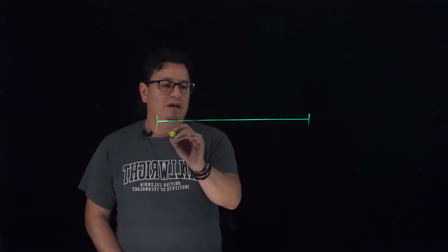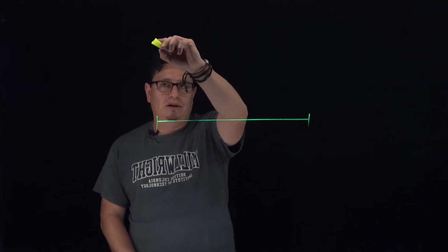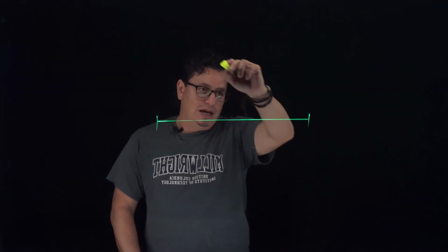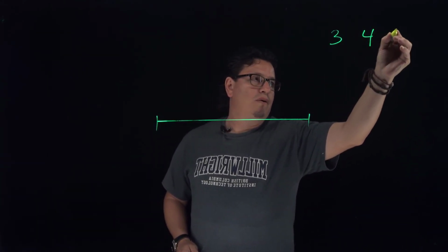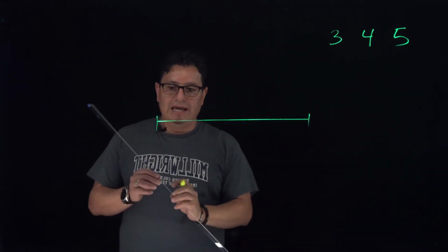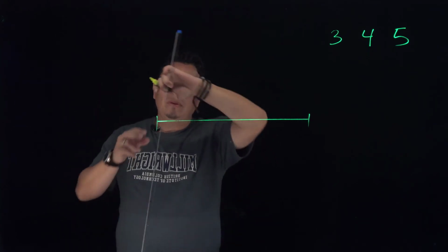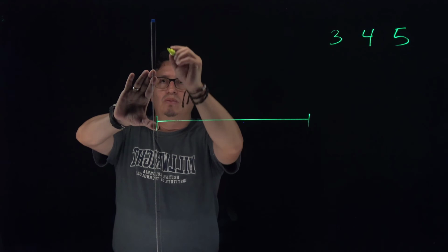If we have this line here as our main center line, we would come with a perpendicular line up here and with a long straight line, which is the hypotenuse in a triangle, which will add to a number, and the number is 3, 4, 5. Your shortest leg would be 3, the longest leg would be 5.